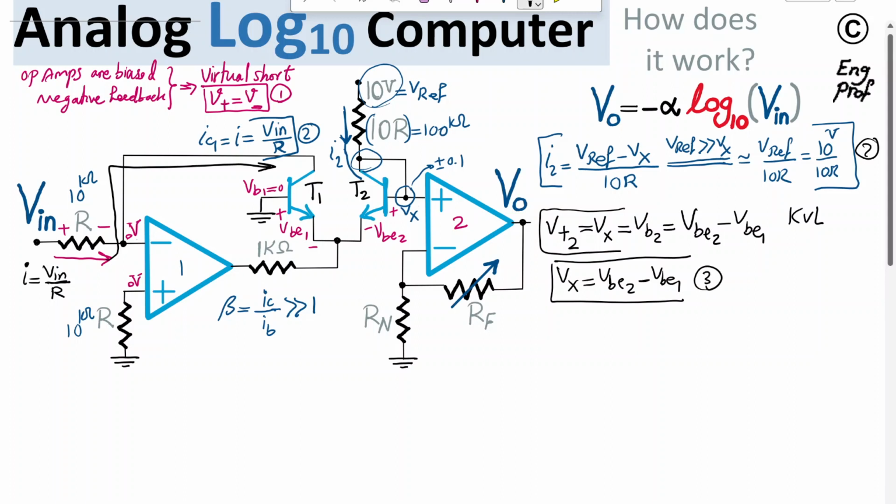For this one, I need to replace VBE, the voltage of the base emitter PN junction of the transistors. For that, I am going to use the well-known Shockley junction current voltage equation, the p-n junction equation that is applicable for bipolar transistors as well.